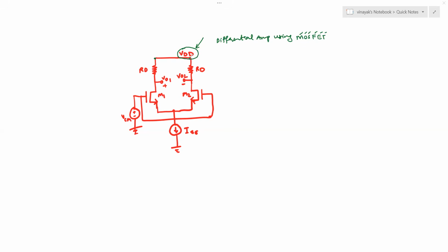So what you see, you have this voltage source VDD that is connected as shown, and to the VDD you have one end of the two identical resistors, which are called drain resistance because they are connected to the drain pins of the MOSFETs. So here that is the drain resistance RD. So that's your drain pins. These are your gate pins and these are your source pins.